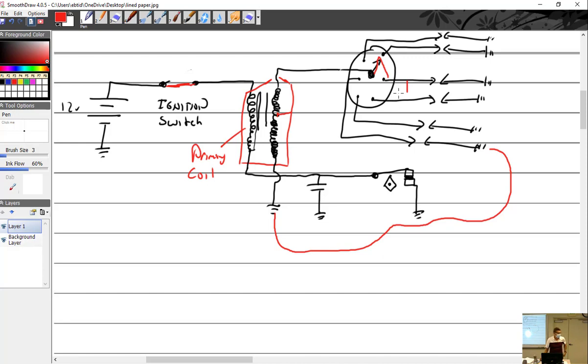So when you're playing with magnetos, and magnetos are the same concept, and you're just sitting there kind of spinning it and turning it and sparking it, it's got to be firing somewhere. And it is, inside somewhere. And so you're just damaging it. Every time you do that, you're creating a weak spot inside of it. So on airworthy magnetos, don't do that. It's a bad thing.